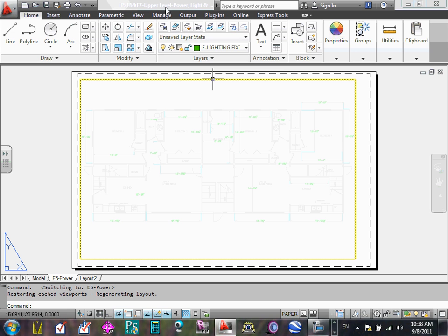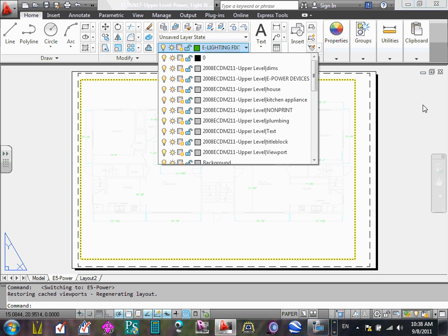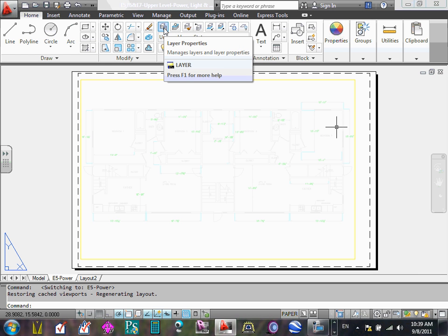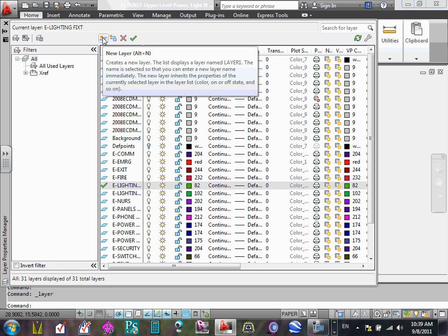Okay, I'm going to go to the title block. What I like to do, did we have a layer that says title block, guys? I don't think we created a layer. Okay, when I bring the title block as an XREF, I like to always put it on its own layer. So can you guys come over here one more time, please? See that? Everybody's there? Click on layer properties, right there. Cool. Yep. Click on it. And when we go there, we're going to create a new layer. Everybody knows now, create a new layer.